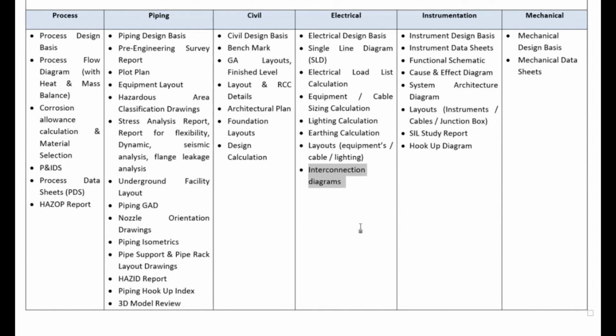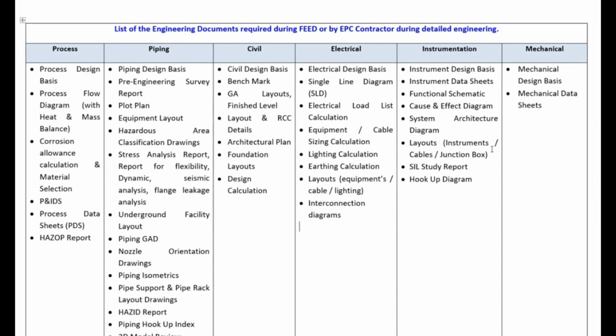It's basically more detailed drawings of the electrical equipment and electrical interfaces with instrumentation. So that is called interconnection diagrams. So this was about electrical. Then instrumentation drawings, instrumentation design basis, yes. The instrumentation data sheet is prepared based on the process data sheets, as I said.